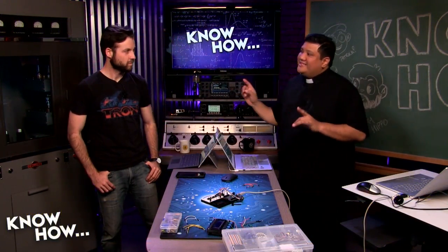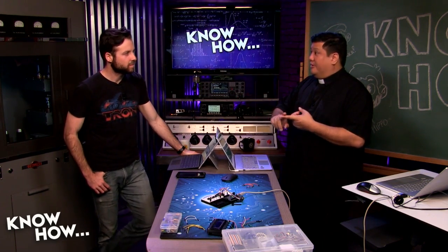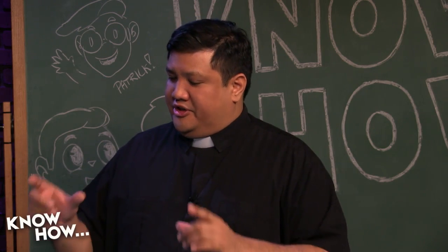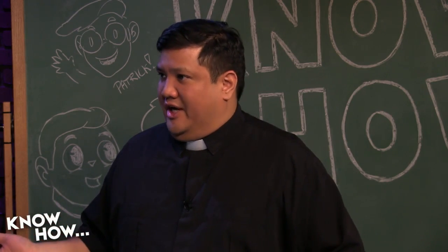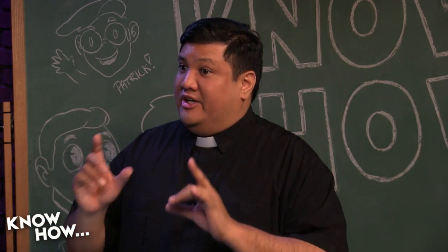Brian, there are 3 types of memory in an Arduino. There's the flash memory, and flash memory is where we store the program. So when I upload a sketch to my Arduino, it's going to store it in the flash, and flash is non-volatile, which means it will be saved until I overwrite it. That program stays inside the flash memory. If it loses power, it'll be saved. That's why I don't need to re-upload the code to an Arduino every time I turn it off. That part is safe.